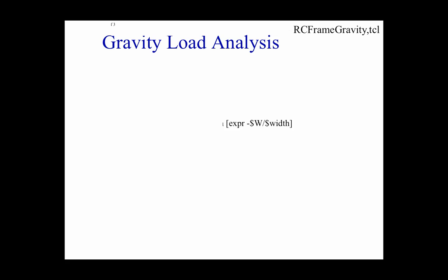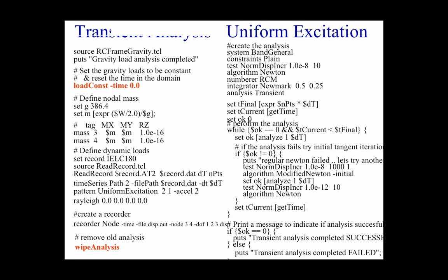Those commands were in the file rcframe.tcl. So if we want to do a gravity load analysis of this frame, we source in rcframe.tcl. We create our load pattern, create our analysis object, and perform the analyze. And then we want to do transient analysis with load control. The only thing I will mention is that at the end of gravity analysis, what I'm going to do is